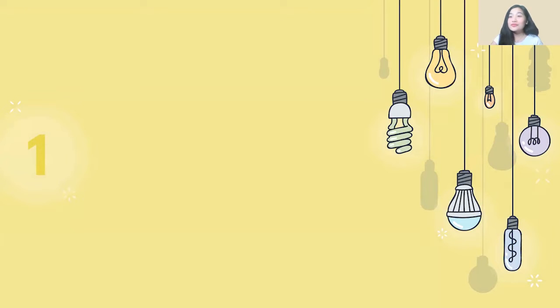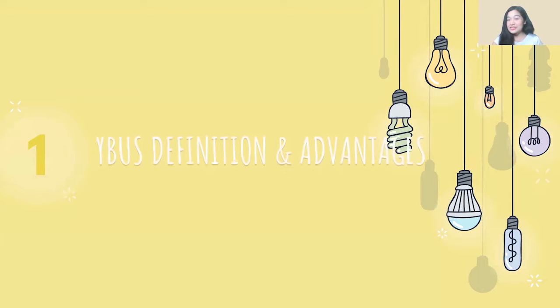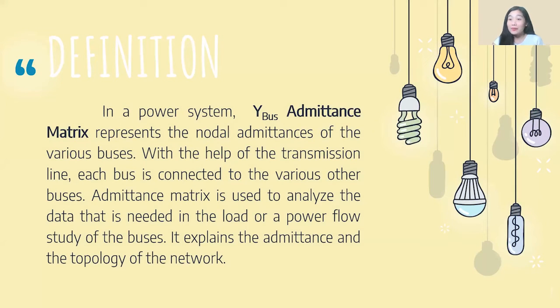Okay, starting off with our first destination, I combined the second: the definition and the advantages. So let's start. The definition in the power system of the Ybus admittance matrix is that it represents the nodal admittances of the various buses. In this first sentence, we can dissect the Ybus. There's admittance, which is the reciprocal of the impedance. There would be nodal admittances to be specific, and there would be an interaction with the buses.